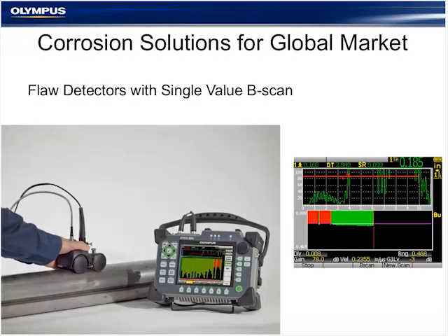There are some thickness gauges that can take advantage of what we call a B-scan buggy. So that's this little wheeled cart that you see here in the left side image. Essentially what this allows you to do is record position information along with the thickness reading from the transducer. So this buggy would drive down the length of the pipe or be pushed down the length of a pipe, and it will report back to the flaw detector not only the ultrasonic data via the transducer, but also the position information along the length of the pipe. So it does give you essentially stripe measurements of your pipe, and you can get a profile of that section of pipe to give you an idea of what level of corrosion you're dealing with.